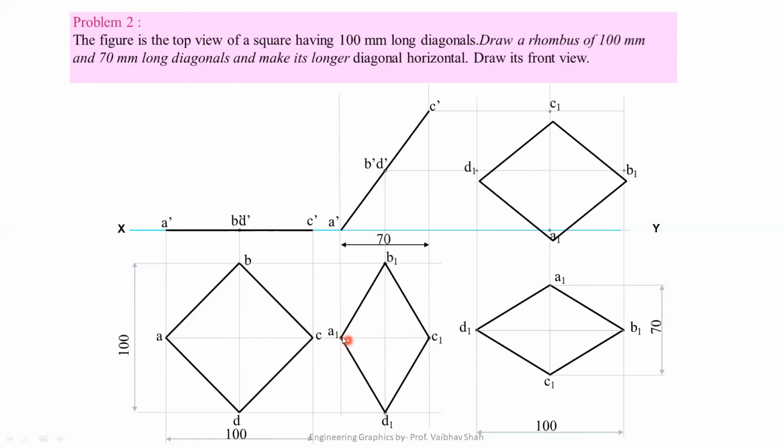Try to locate this point A1 on this horizontal line and try to cut this 70 mm long diagonal distance on the rounder. On this horizontal line, we'll be having this point C1. After getting this point A1 and C1, try to reverse this drawing. So we'll be plotting this vertical line from your A1 to obtain this A1 dash or A dash, which is the starting point of your inclined surface. And as we know that if your surface is inclined, your C1 dash point will give you point C dash on this inclined line somewhere here. To get this inclined line, we will be taking the dimension of A dash to C dash and put your rounder at point A dash and try to cut this line of C1 at point C dash here. So we'll be having 2 points A dash and C dash.